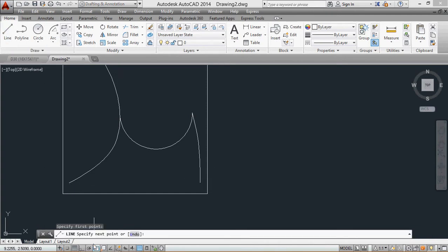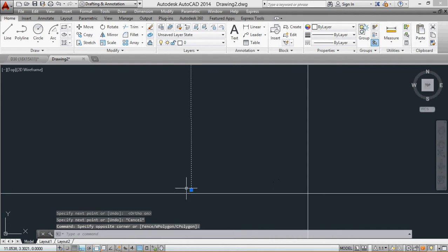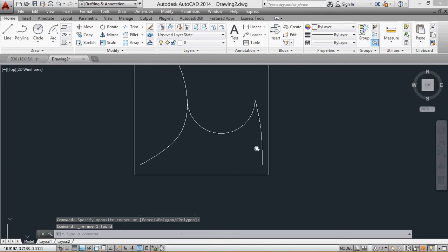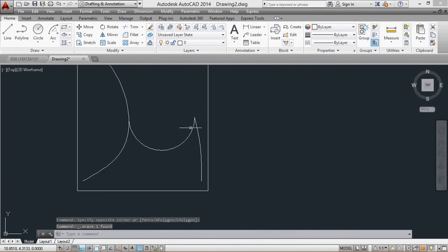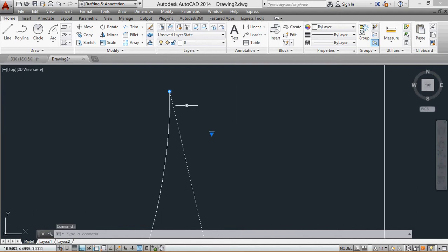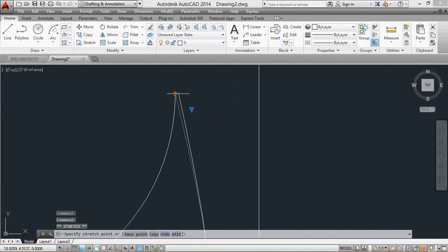Again, you have to make sure it is straight, 90 degrees, so you go to your ortho command, turn it on. Draw a reference line, stretch this item down by clicking the blue point, stretching it down to snap onto the horizontal line. Alright, so we have these 3 different parts. If you want to change this to have a little roundabout arch, that would probably be a good idea.